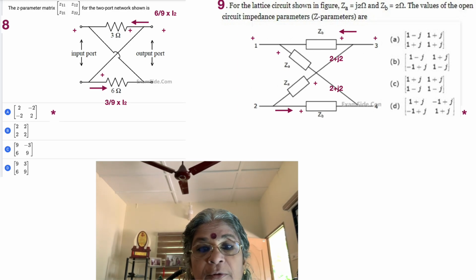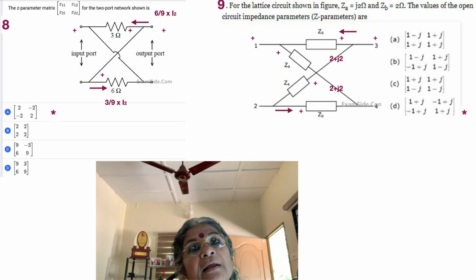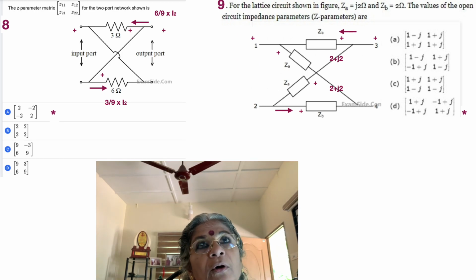I suppose that's clear, and that gives us the voltage. So that will bring us back to terminal 2 of port 1. So it's very easy to see what the voltage is. Of course we know that because the impedances are equal, I is going to split into equal halves, because ZA and ZB are going to be in series for both the paths for the current.